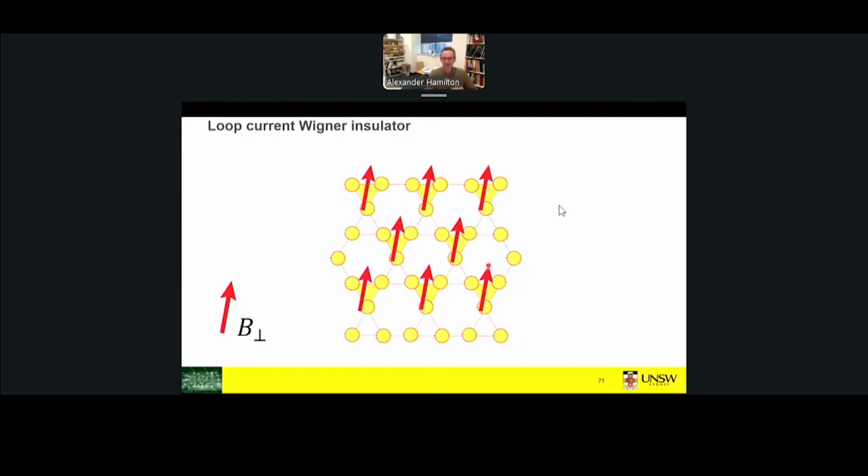We can control the chemical potential with the pattern gate, which also affects the intersite hopping through self-consistent Poisson-Schrödinger physics. And we can control the strength of the modulation potential, which essentially changes both U and T. So you're right, we don't have full independent control of all 3 things. To change that, the easiest way would be to change the lattice constant a bit. Yeah, okay, thanks.